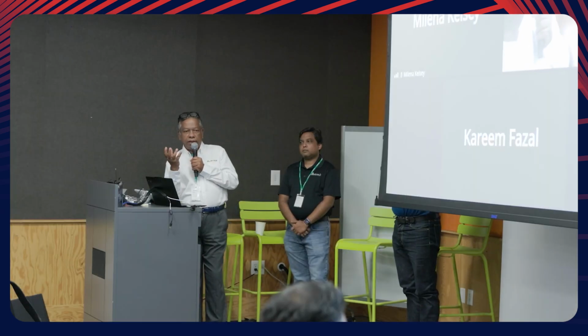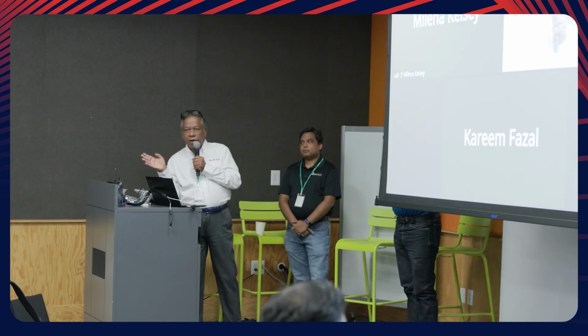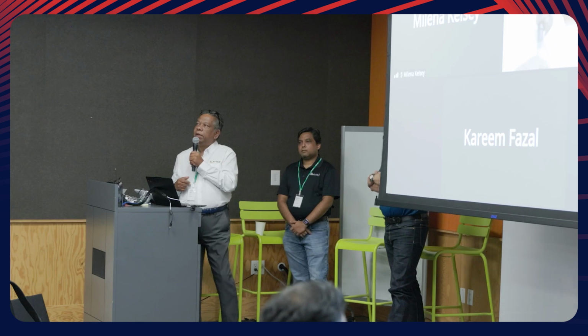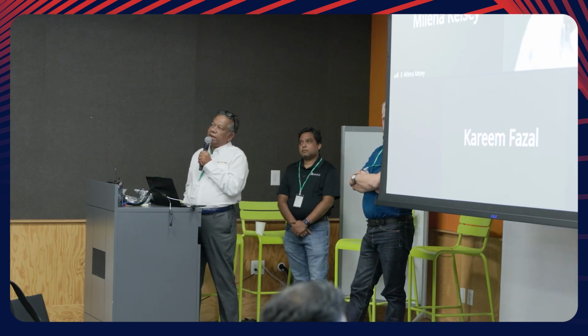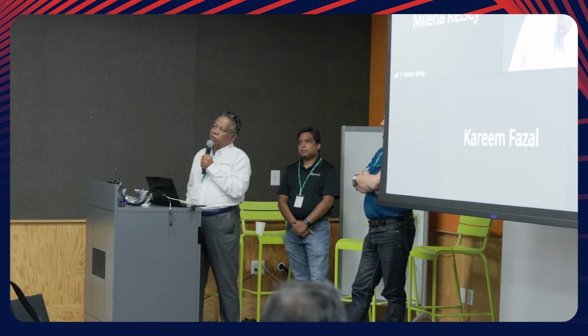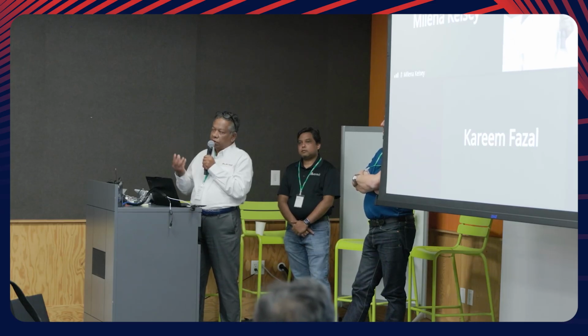So that way you truly decouple your BMC, because you don't care about the underlying hardware anymore, right? You don't care about the physical layer. We only talk one language, right? So right now it is targeted at the DC-SCM. So it's still the DC-SCM form factor. The only thing is that you have a BMC, and then you have something that can translate your OBMF ICP spec, right? That's what it is.